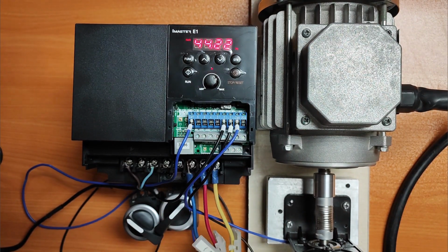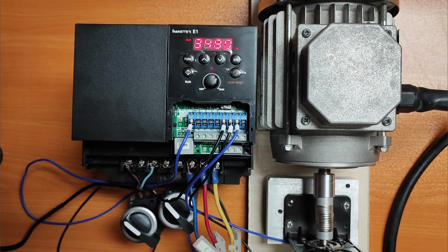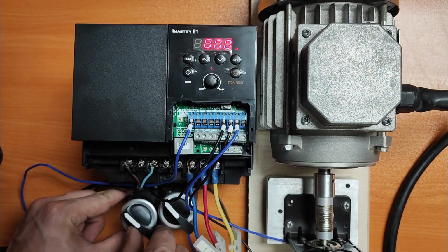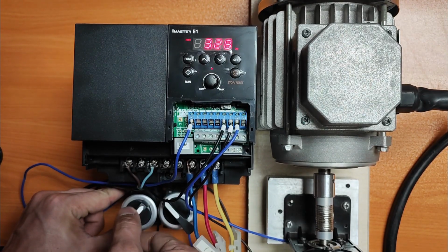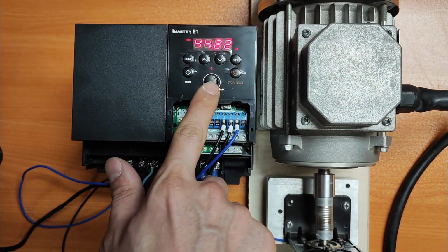Alright, now if I want to start the inverter in the opposite direction, first I'll need to manually deactivate digital input number 1. The inverter comes to a complete stop, and then I manually initiate the operation of the inverter again in the opposite or reverse direction. As we said, this digital input is for the reverse direction. Now, if I activate it, you'll see that the rotation of the electric motor changed, and it started in the reverse direction.